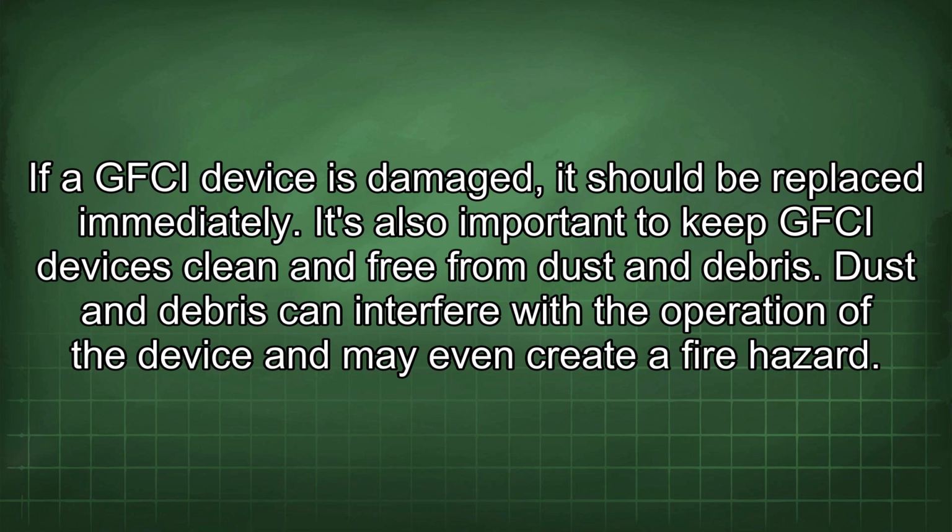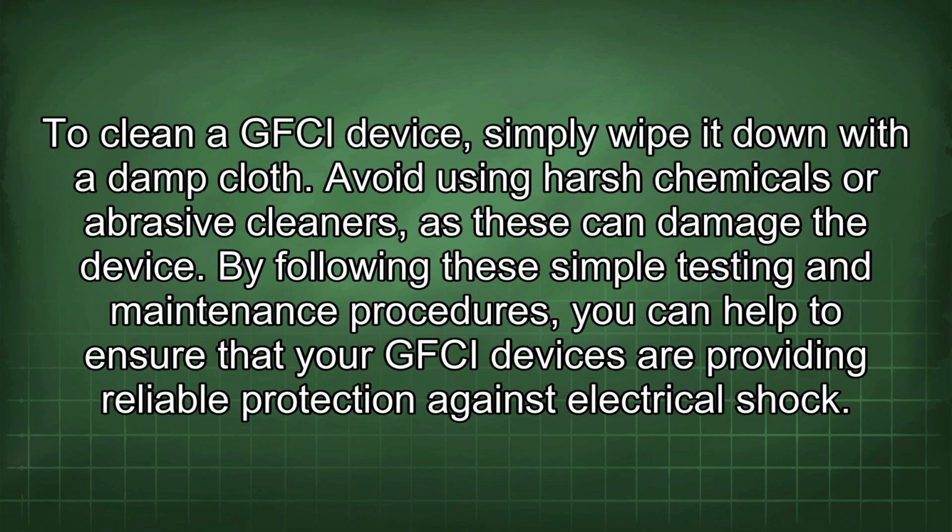It's also important to keep GFCI devices clean and free from dust and debris. Dust and debris can interfere with the operation of the device and may even create a fire hazard. To clean a GFCI device, simply wipe it down with a damp cloth. Avoid using harsh chemicals or abrasive cleaners, as these can damage the device. By following these simple testing and maintenance procedures, you can help to ensure that your GFCI devices are providing reliable protection against electrical shock.